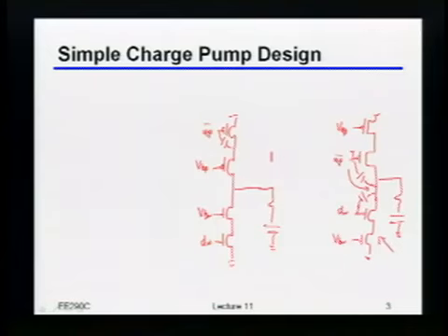You just make the switch in saturation region. Okay, well, but that is actually what this VBP is trying to do, right? Because this VBP is just trying to bias that thing to look like a quote-unquote current source, right? Is there anything else you might be able to do?